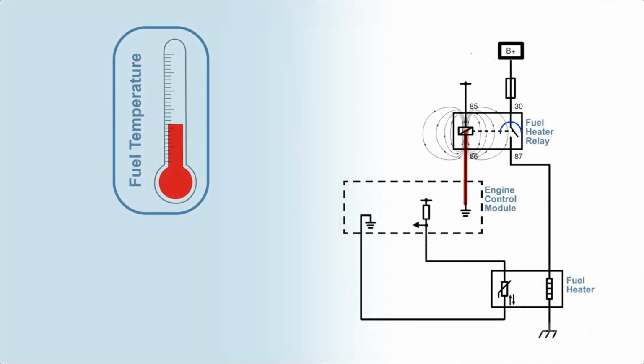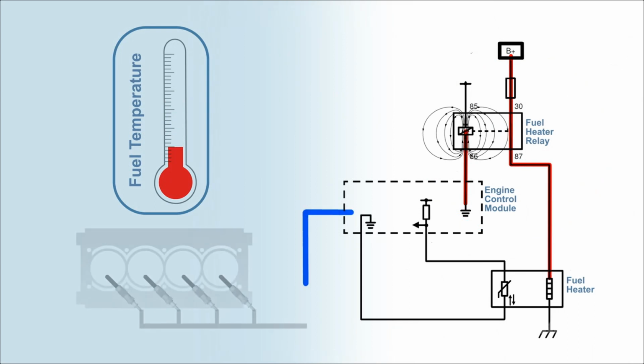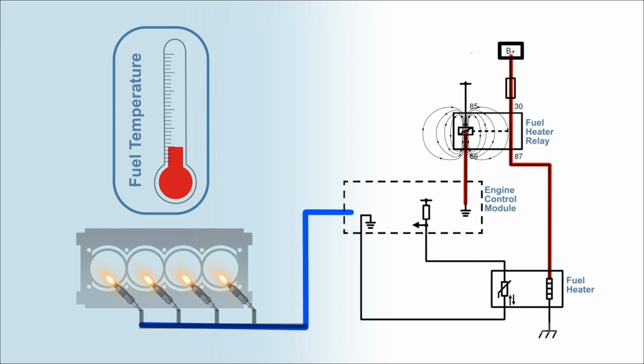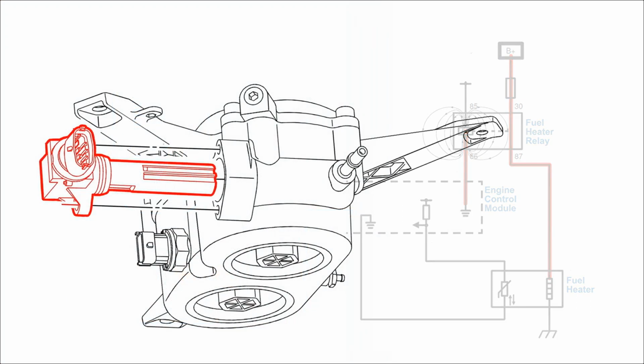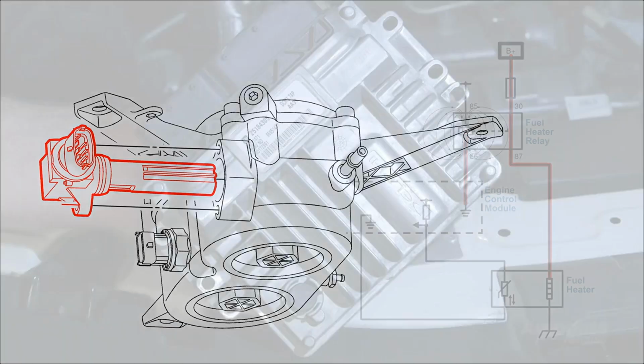Fuel temperature will determine if the fuel heater needs to be turned on. This data will also be used in determining glow plug operation. The fuel temperature sensor and the fuel heater are in the same housing, which is mounted in the fuel filter.